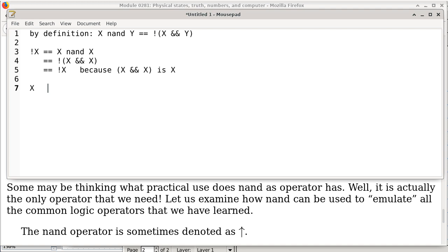And then on the other side, we say, okay, if I know what x is, do I know what is the negation of x, which is what we want to achieve. And we also want to know what is x NAND x. Now, x NAND x is by definition the negation of x and x. So we want to work out these columns. There are basically three columns. The first column is x. The second column is the negation of x. And then the last column is what we think implements the negation of x, but only using NAND.